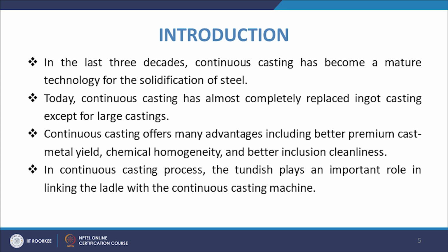It offers many advantages, including better premium cast metal yield, chemical homogeneity and better inclusion cleanliness. As for the terminology, better premium cast metal yield: as you know, in normal conventional casting the casting yield is not very high because of the removal of gates and risers and other things.